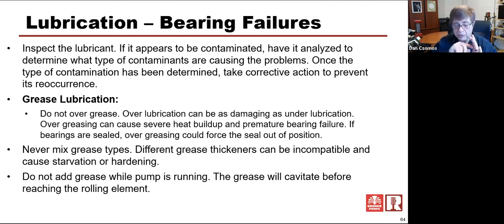And you don't want that, because you're going to create scratches in the ball bearing itself, and also in the race. So you want to be careful about over lubrication of grease. You don't want to grease too often, and you want to grease when that bearing is off. If you have the opportunity, it's really nice to be able to grease the bearing and then rotate it by hand a little bit before it's turned back on. Make sure you lock out a motor before you go greasing bearings and turning the shafts.